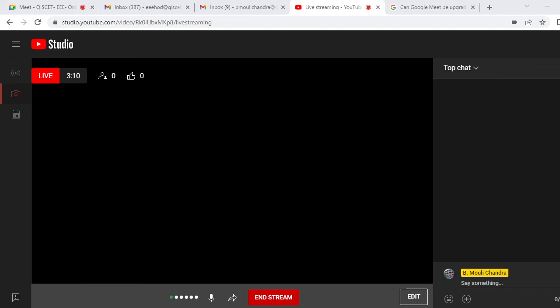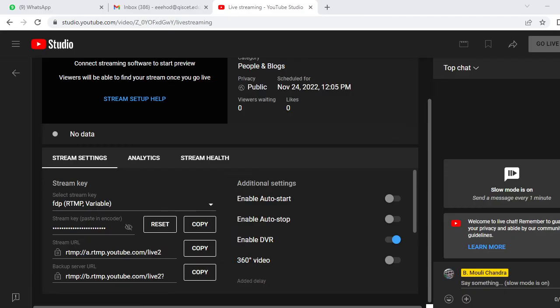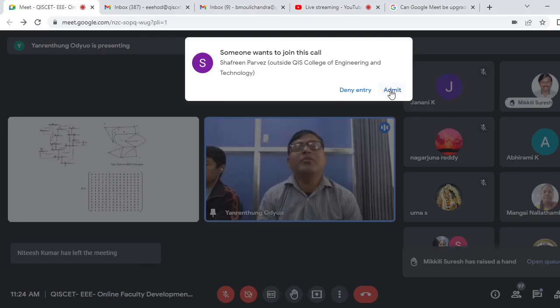Now here this is a 14-bus network. This is the graph equivalent for the 14-bus network, and this is the adjacency matrix. Adjacency matrix means what? We are having rows and columns. In the column we are putting nodes, and in the row also we are putting nodes. Now we have to check the connectivity between the I node and J node. If there is any connectivity, then we put one. If there is no connectivity, then we put zero.